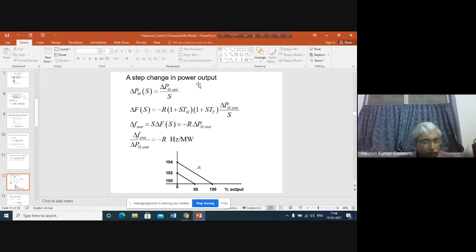This much power it can generate because we have described the function of the speed governing mechanism. When the speed of the generator changes, the position of B will be changed. Accordingly, the position of C will be changed, the position of D will be changed. As a result, E will be changed, and as E is changed, the opening of the steam valve will be changed. The governor on its own can do this operation. This is called the throttling operation of the governor. So because of the throttling of the governor, there will be more steam entering the turbine. As a result, there will be more power generation.